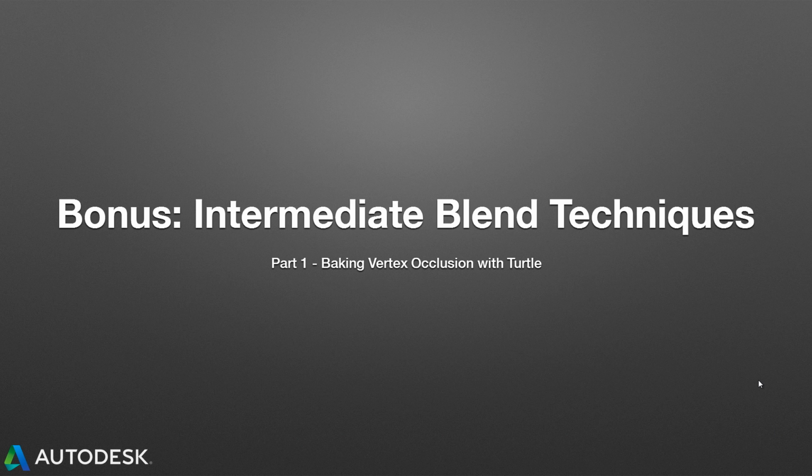When we paint our grime using the vertex colors, it's important to remember that we want an accurate representation of where we would expect it to gather in real life. Typically we would see quite a bit under the windows, overhangs, or in corners. This corresponds nicely with where we would expect occlusion shadowing to occur. Because of this, we can use Turtle to bake an occlusion pass directly to the vertices, eliminating some of the hand painting required to give our mesh a nice realistic weathered look.